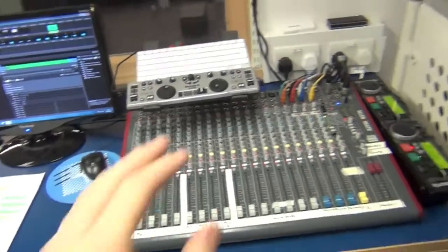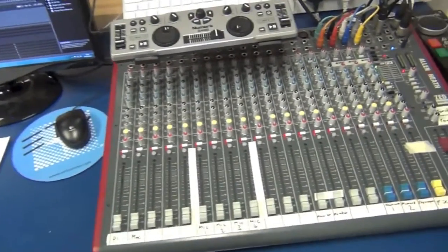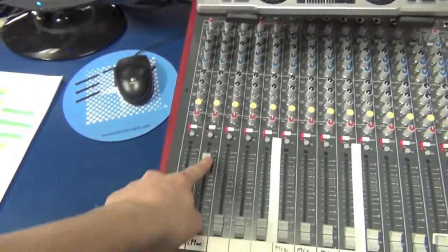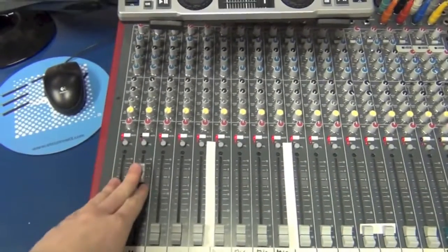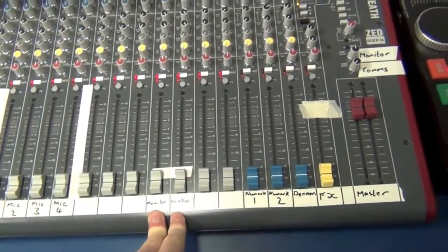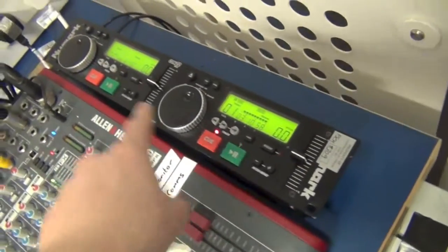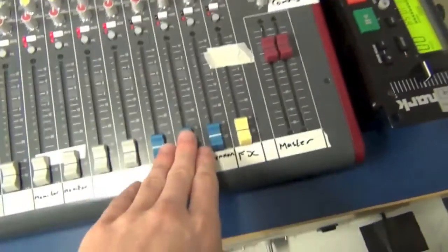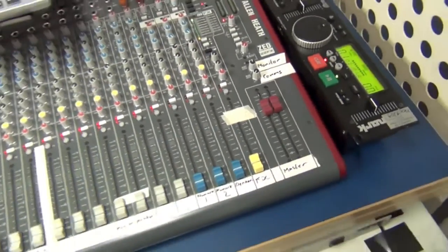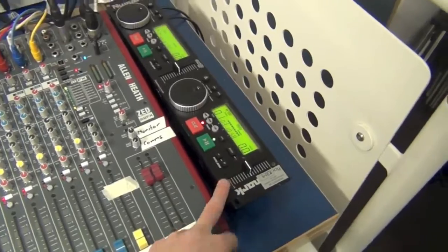First of all, here we have an Allen & Heath Z22FX. This is our main sound desk. We're not actually using that many channels. In fact, I'm only using one main audio output, which goes straight from the computer, and then these two channels here are monitor channels, which run up to our monitoring in here. We've also got a CD player here, a Newmark dual CD player, which is connected into these two channels here. That's acting as a backup. If the computer dies, I'm still able to get audio using this CD deck here.